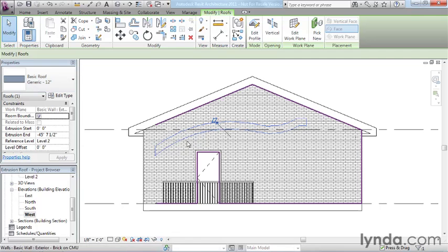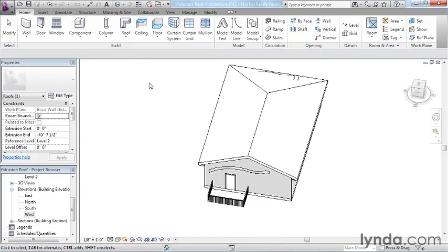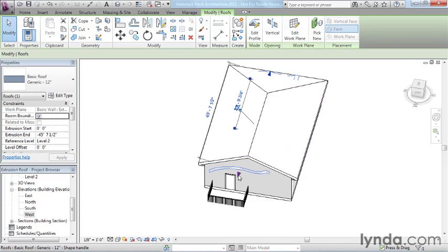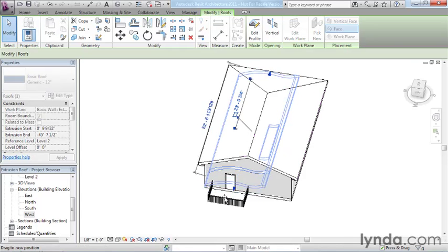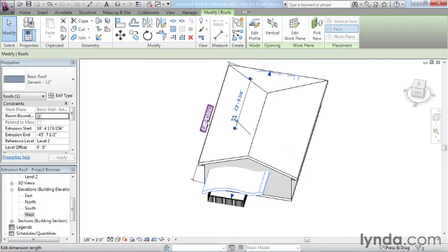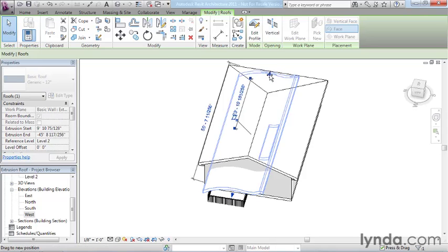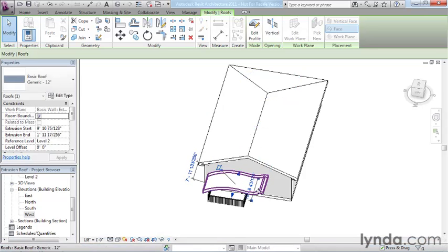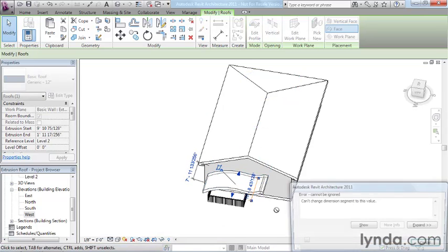Now, it looks a little odd here what happened, and it's a little easier to understand in 3D view. I'm not really sure why Revit always does this, but it always goes the depth of your building. It just sort of has to assume something. So rather than ask us another question, they just make an assumption. And in my opinion, they always assume poorly because I always have to come over here and select this and make adjustments. Now I can do this manually with these little control handles at the end. I can type in numbers, make that 55 feet. I can pull this one all the way out here. Make that 10 feet. Whoops.